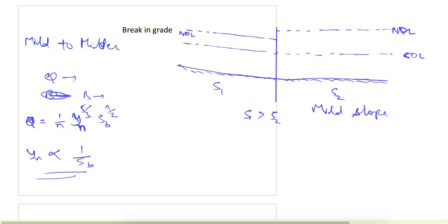If we are letting our water flow freely, it will always try to attain the normal depth line, and because this normal depth line is not affected by the control section, this will just be carried on the normal depth line, but it will be disturbed in this zone, so the flow will try to achieve this normal depth line here.